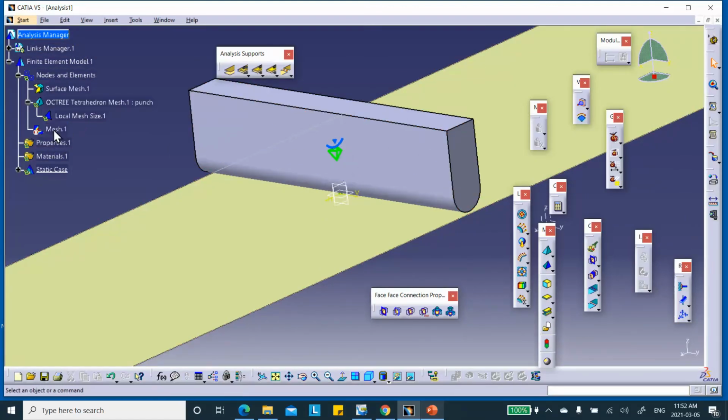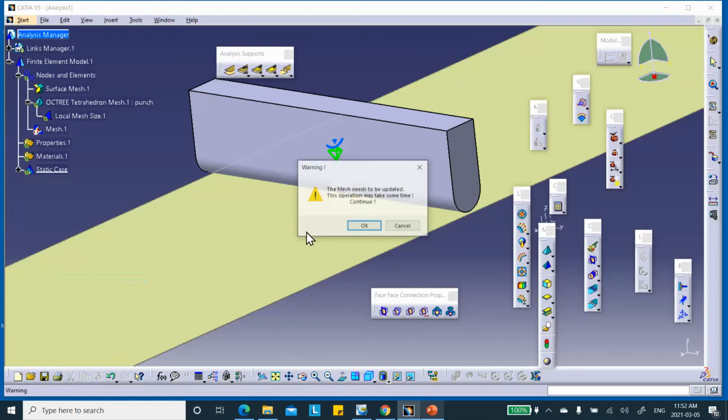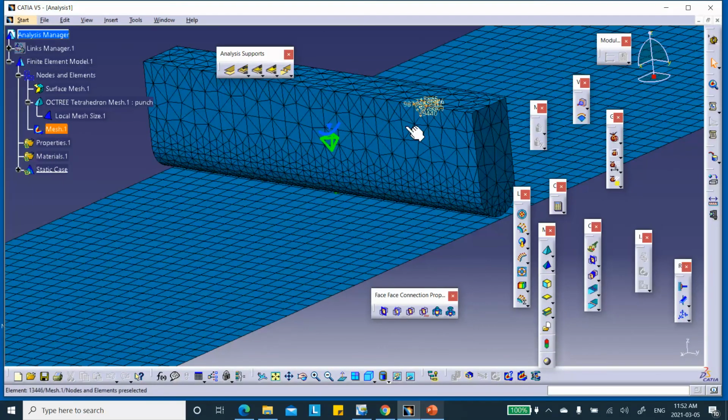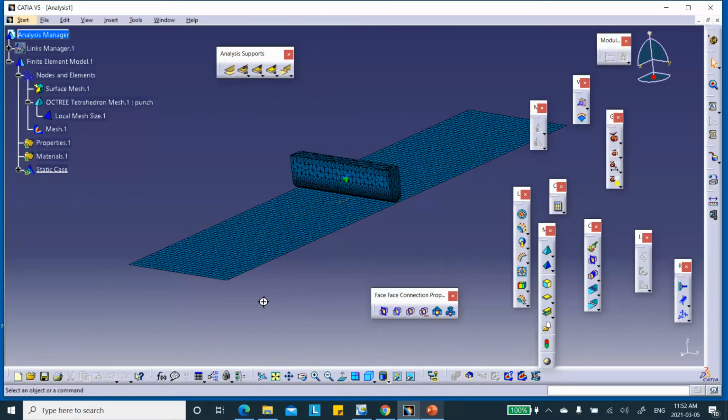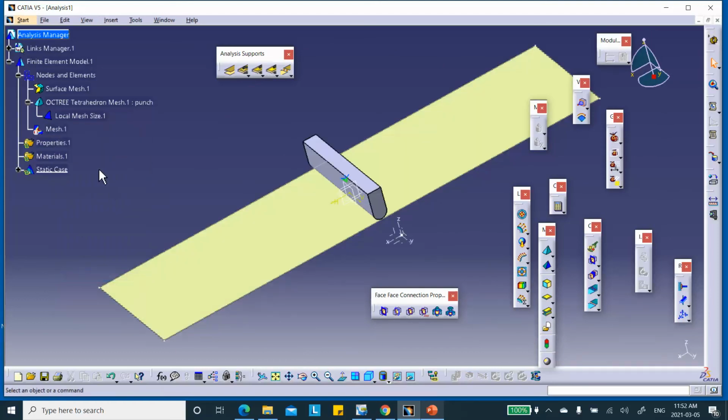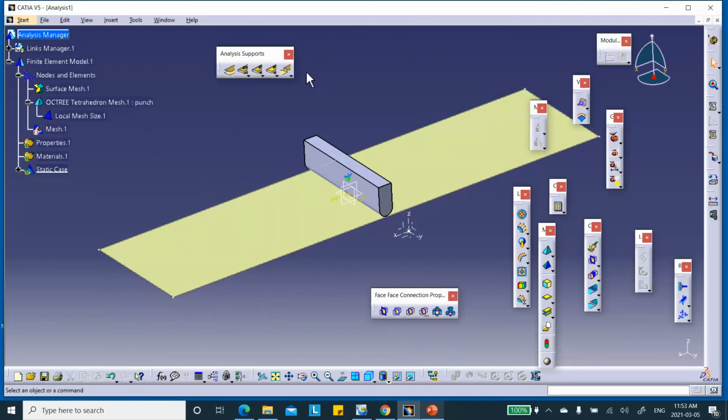Okay, now look at the mesh now. So right click mesh visualization. So you can see that this is the original mesh with 10 millimeter. Then I made a local mesh refinement down here. And of course, this is my shell mesh. Okay, good. Deactivate this. Now, here's what I was talking about. Unfortunately, because of the way I did it, if I had come here first, it would have meshed this thing exactly as it's supposed to be, and it would have picked the right material, which is steel, by the way.